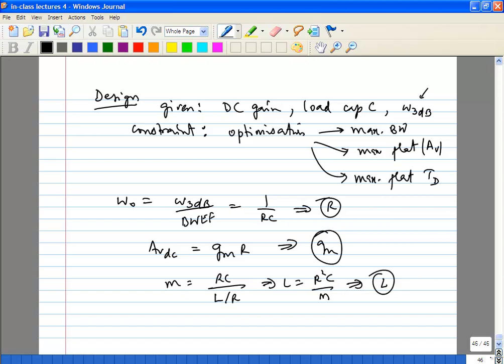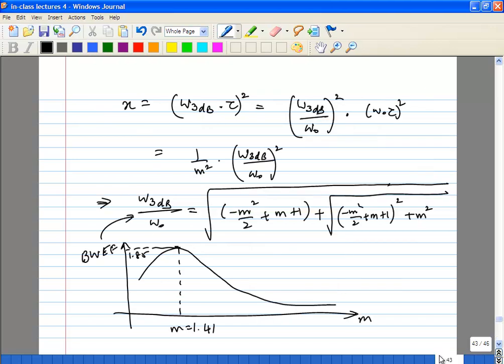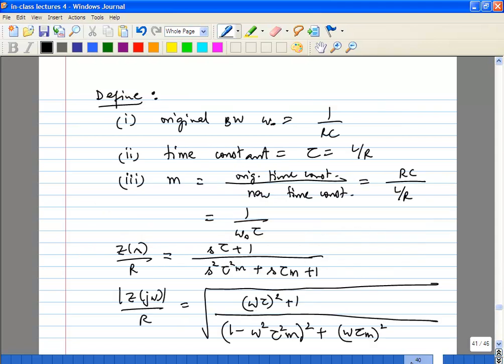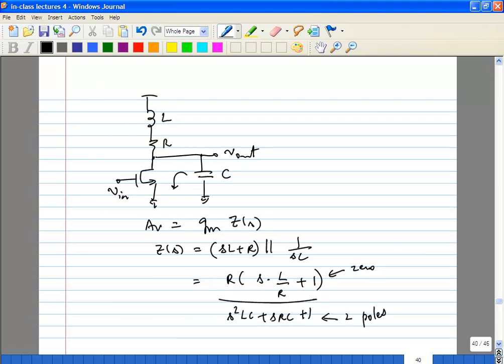Now the other thing to remember is, if you go back to your amplifier, unlike your narrowband wireless RF circuits, in this case you actually have an explicit resistance in series with the inductance. In other words, you don't care much about the Q of the inductor.